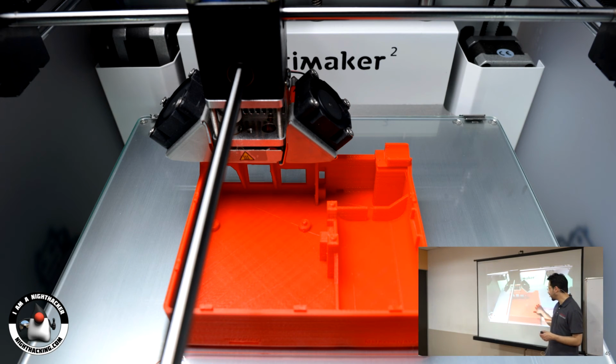The whole design of this case is it's designed so you don't need any support material to print it. So everything's designed so when you're printing, there's something below it that you can build layers on top of. If you print in the air, you get a big mess because there's nothing to support the material. Some cases are okay though, like you see in the back here, those openings, it prints across, it does what's called bridging to go across that.